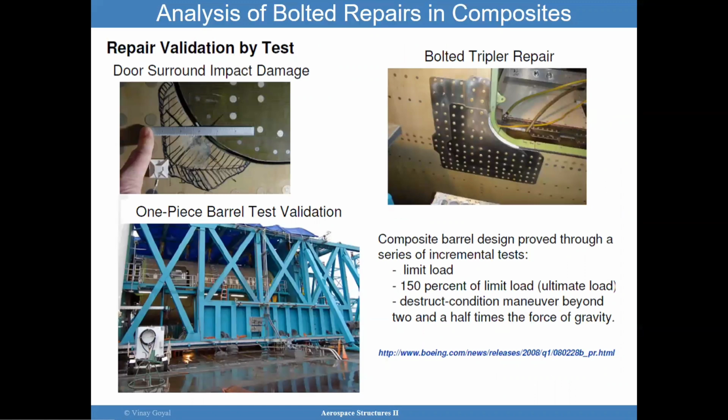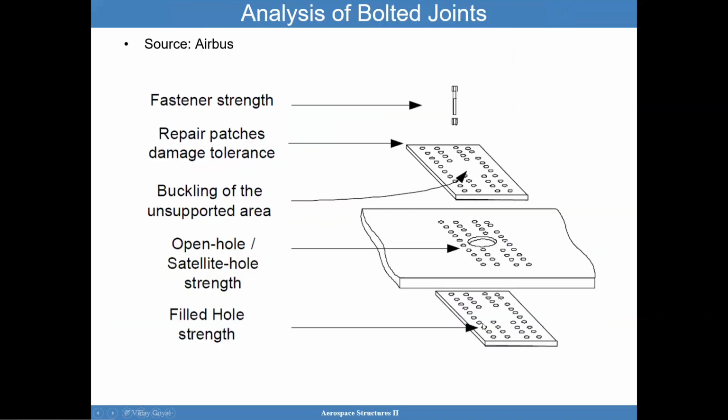You also want to validate the repair through testing. In this example, this repair was then bolted and then tested quite a bit. They took it up, in this case, to 150% of the limit load. Pause the video and feel free to go check it out. But in essence, you want to make sure the repair is robust. Here's an example of an Airbus repair.